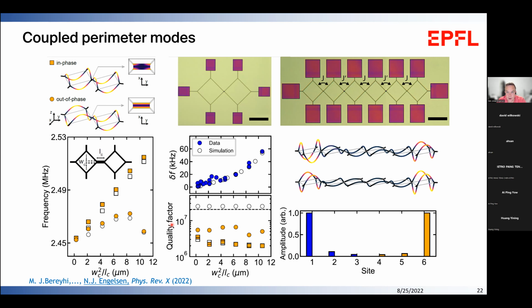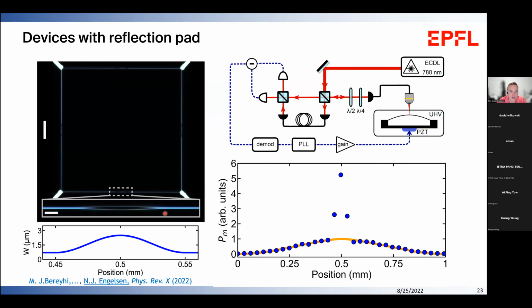polygon resonators. So I said earlier that it's much easier to interrogate membranes optically than strings. And this is because the strings we make are very narrow. The polygons, for example, are only 200 nanometers wide. So this means it's very difficult to make an optical spot that's small enough to get an appreciable reflection from the devices. While we can easily characterize their quality factors, it's maybe harder to do something useful with them with free space optical interrogation.